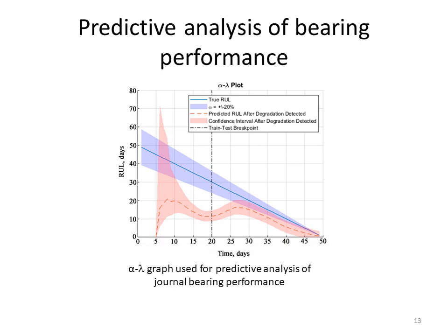The confidence interval boundary, shown by the dotted line in the figure, crosses the threshold already on the 40th day of the beginning of operation. Therefore, it can be stated that after 40 days of operation, further operation of the bearing is unsafe.